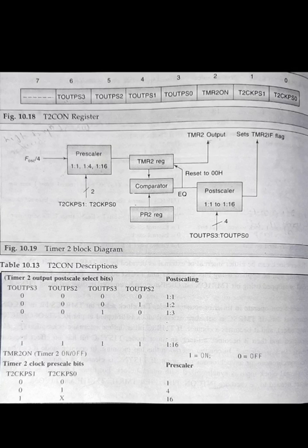Timer 2 has the 8-bit period register PR2. Timer 2 increments from 00 until it matches the PR2 value, and is then reset to 00H during the next increment cycle. Upon reset, PR2 is initialized to FFH. PR2 can be read or written. The match output of TMR2 goes through a postscaler of 1:1 to 1:16. Any match generates an interrupt, TMR2IF, if it is enabled.